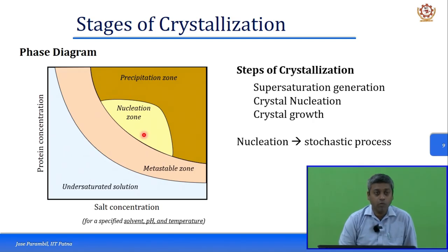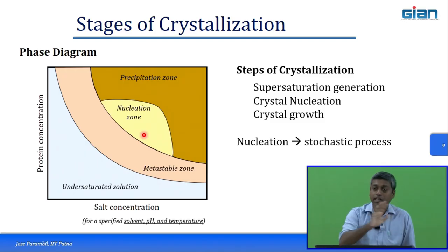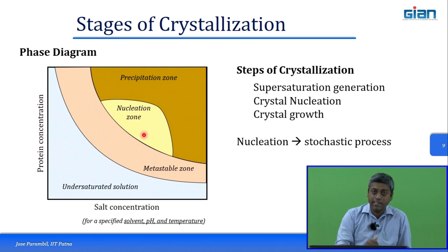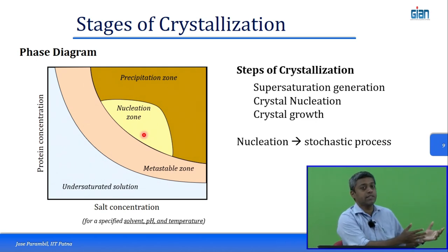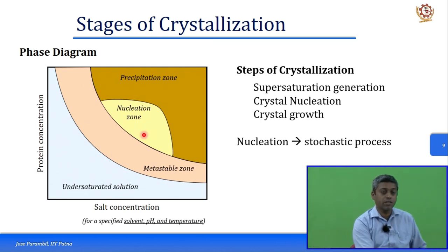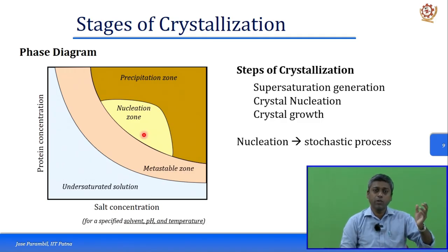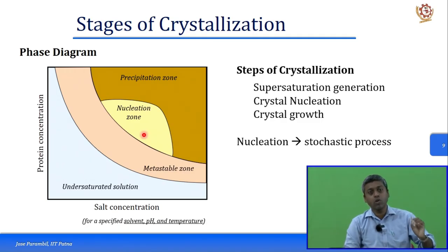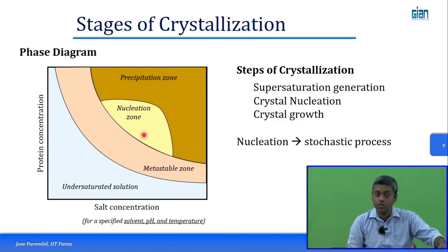But of course, there are ways in order to control that. In some cases you can even completely bypass the nucleation or the troubles of nucleation by adding seeds. Let's say you already have pre-existing crystals, maybe from the last batch of production. You take a very small quantity of material from that and put it into this batch which is going to operate.